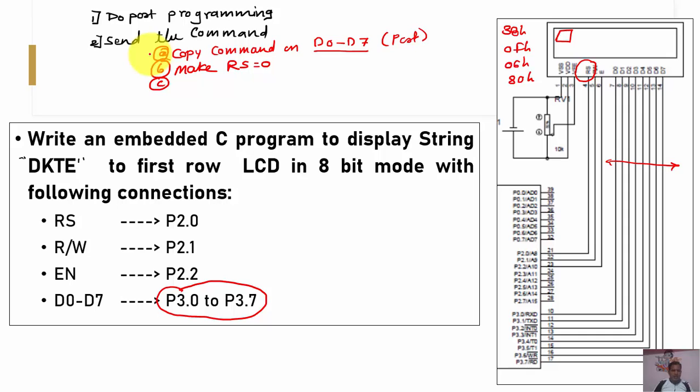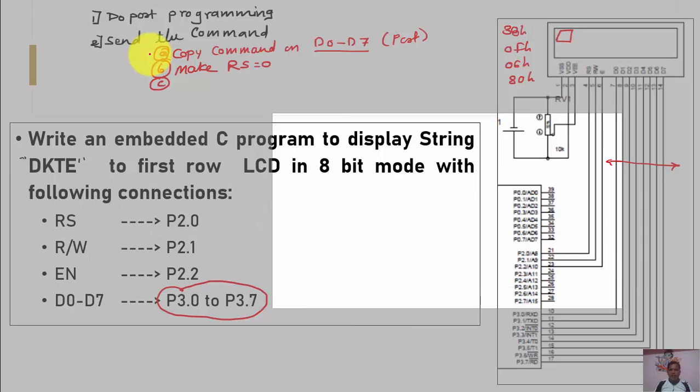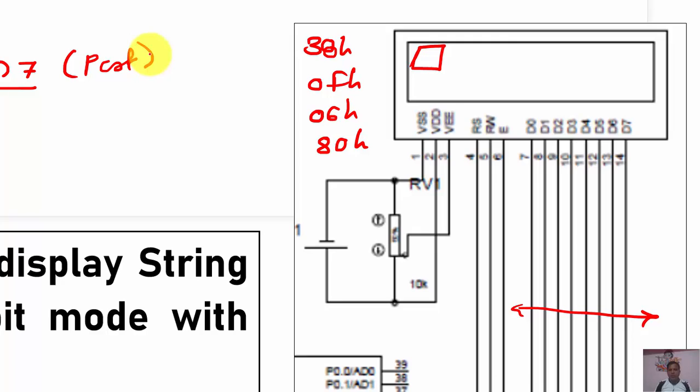The next thing, if I am going to focus on the operation, the operation is simple and straightforward corresponding to this LCD, right? We have to simply follow each and every pin here. First configure RS, then go for R/W bar, and at last EN.